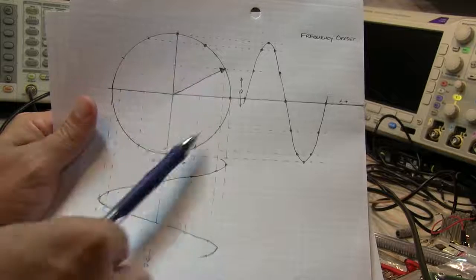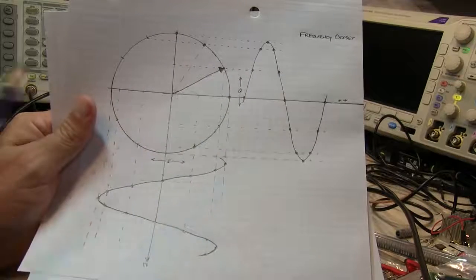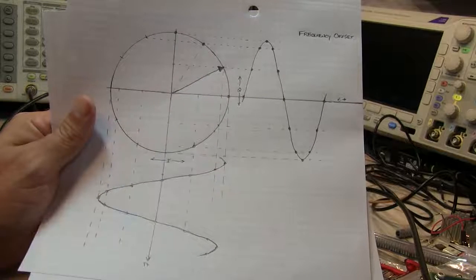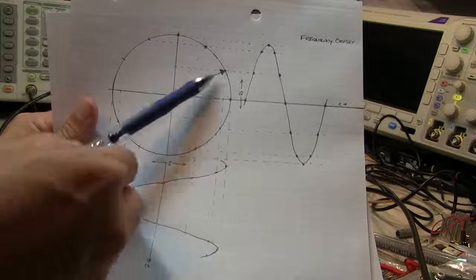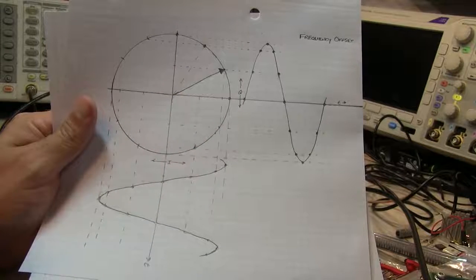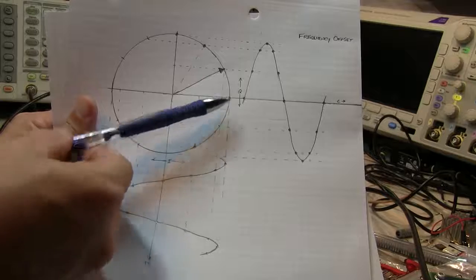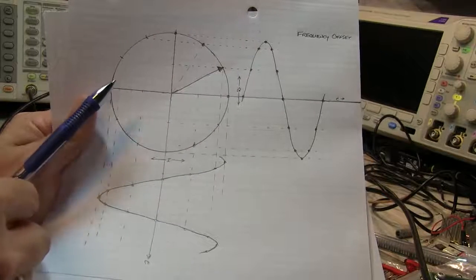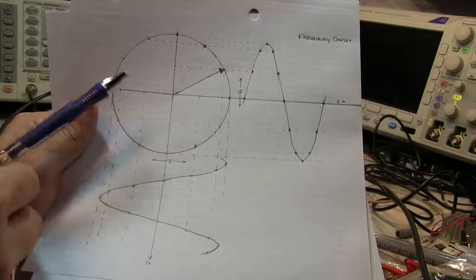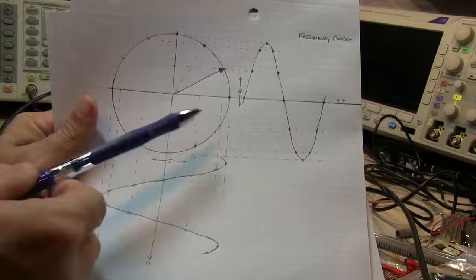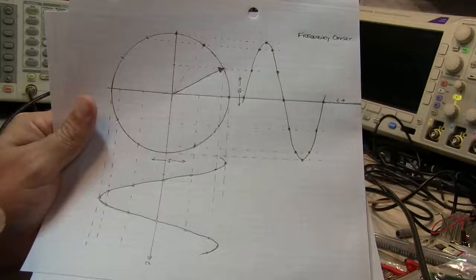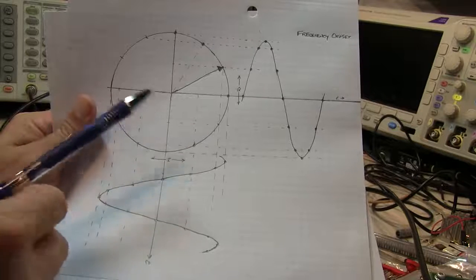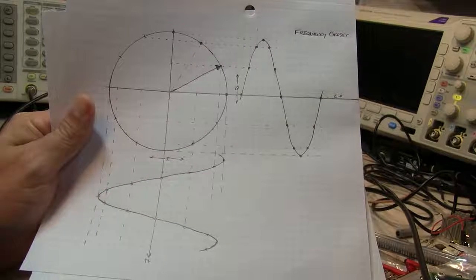Now, how fast that's spinning around is equal to the phase difference between the two signals. Right? If we go around 360 degrees in 1 second, then that's a 1 hertz frequency difference. If we go around 1,000 times a second, that's a 1 kilohertz frequency difference. Now, the direction that we're going around is basically dictated by which signal is leading, or which one is faster. If the I and Q signals are faster than the incoming RF signal, the vector will spin in one direction, and if the opposite is true, the vector will spin in the other direction.